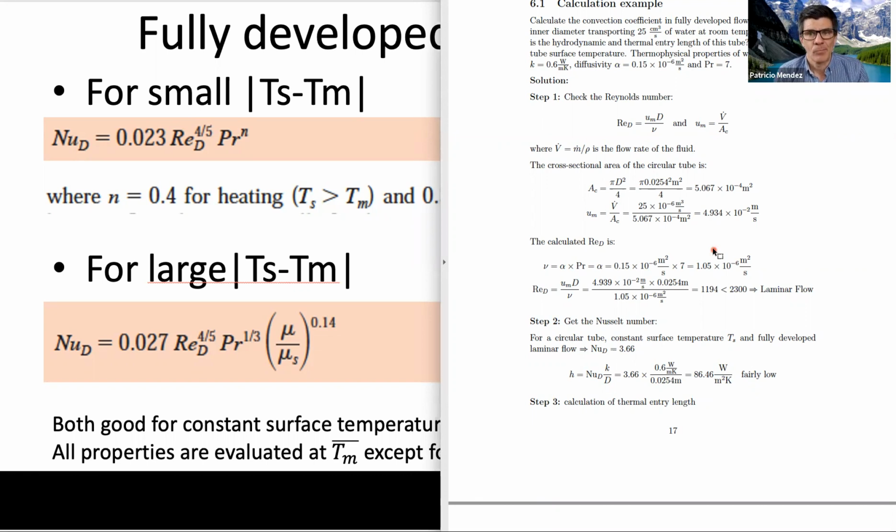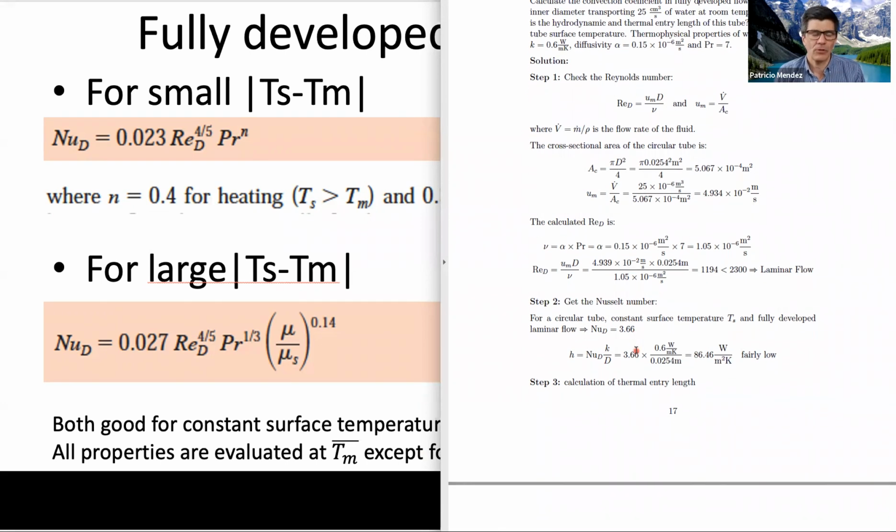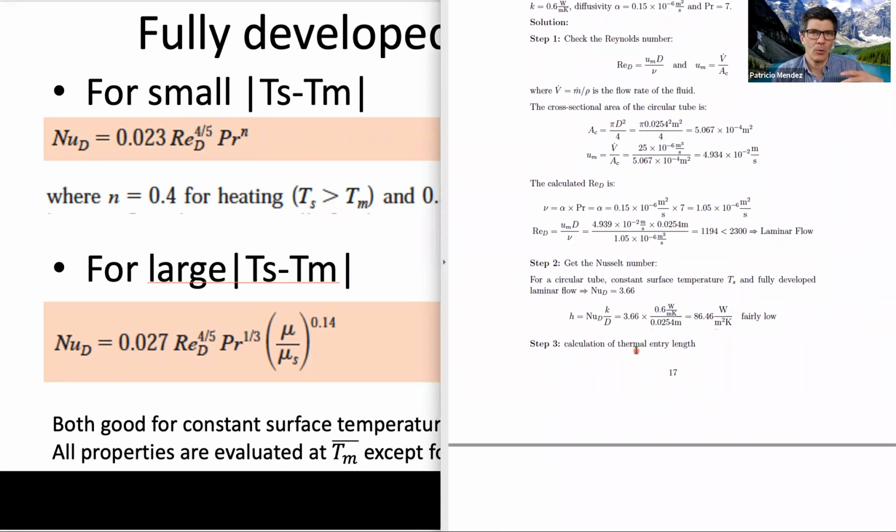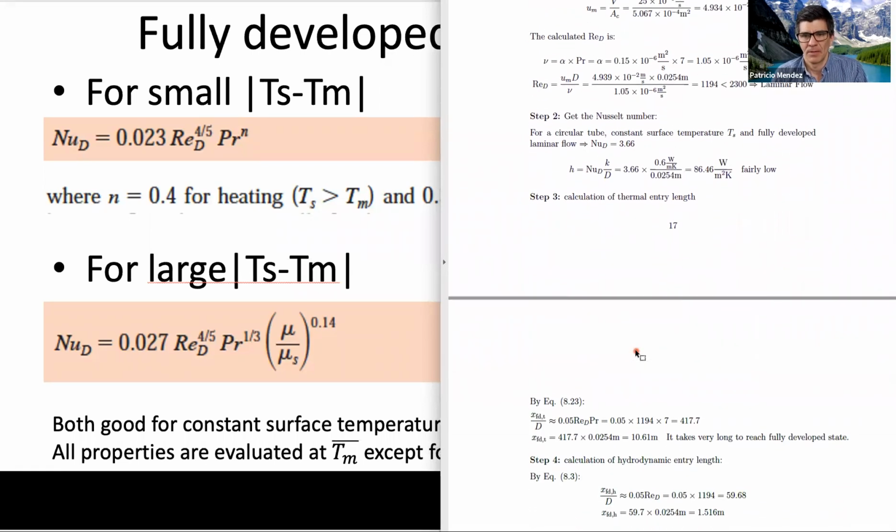But inside the pipes, eventually the flow gets fully developed and the heat transfer gets locked. It cannot get any better, right? So it's good to know, and this would be the exact value to use. If you're designing a heat exchanger, this value would be very much what you measure. This is a real correlation giving you real values. It also shows us the limitations of the things we used to assume just because they were easy to memorize. There can be some error in some of those.